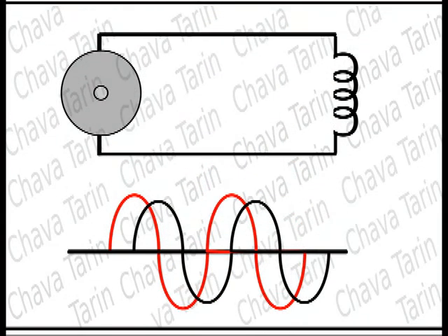If we now replace the resistive load by an inductive load, things change dramatically, since now the current lags the voltage by almost 1/4 of a cycle in a practical circuit.